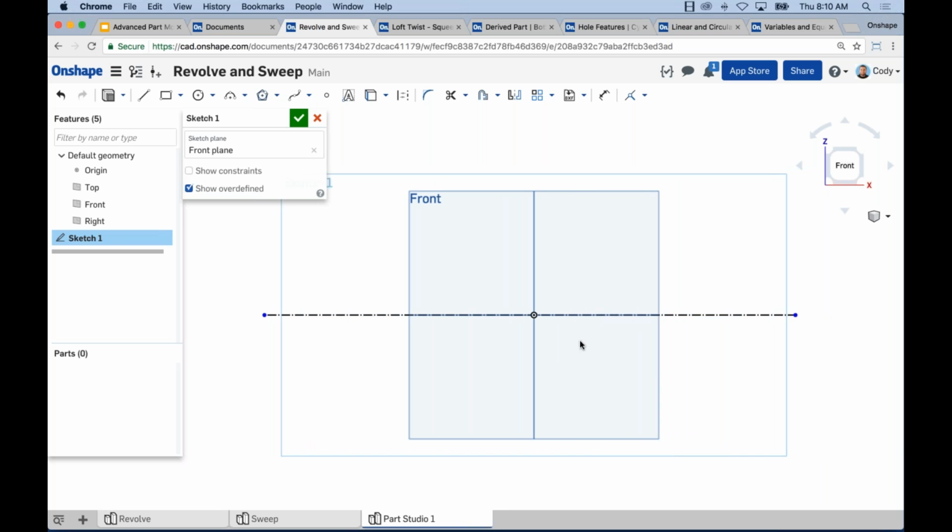All right, now I want to begin sketching the actual shape that I want to revolve. So again, I'll go back to the line command, and I'll just sketch a few lines. Right? So I'm going to create kind of the rough shape that we saw earlier. One big tip that I have as you're sketching, and this is not specific to revolve, but it's helpful in this example, is you'll notice as I'm sketching this vertical line here, I want this inference or referencing the point over here. I want this to be the same length as the one on the right.